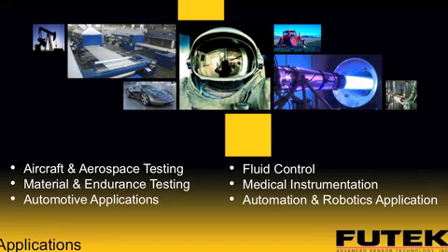As I emphasized in the beginning, the list does go on and on, from measuring ultra-low forces in springs in milligrams or micro resolution to really high capacity measurements. For engineers in the fastening industries, we can use USB to create a correlation between clamping load and torques. For those using multi-axis or multi-component sensors, using USB may be a simpler solution. Here you can again use the Sensit software to measure the load and torques on the same screen. And of course there's a definite cost advantage for this setup.